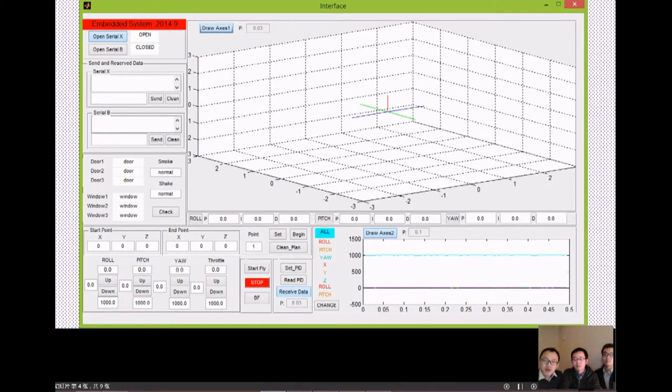Hello, my name is Chang Cui. In this project, I made a MATLAB GUI panel for controlling, monitoring, and debugging the quadcopter through a wired serial port first, and later through Bluetooth, which is the most crucial part of the GUI and I am also responsible for paperwork. I researched copter rotation algorithms like the quaternion method, calculating moving distance, and drawing 2D pictures for essential data and a 3D picture for copter motion. With the wired serial port, the copter cannot fly.